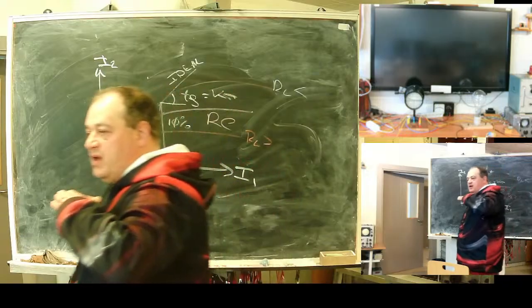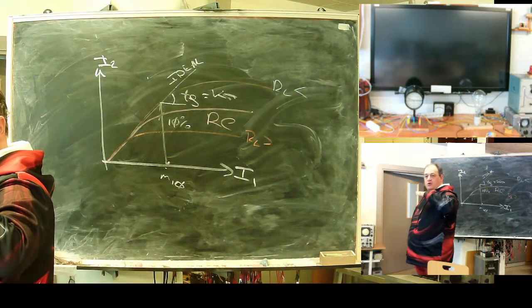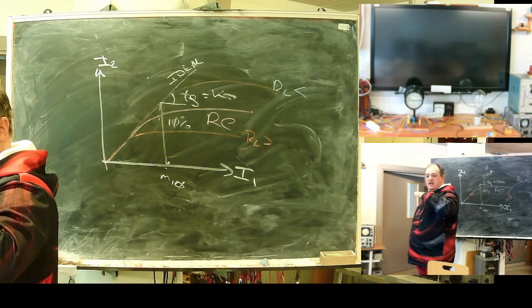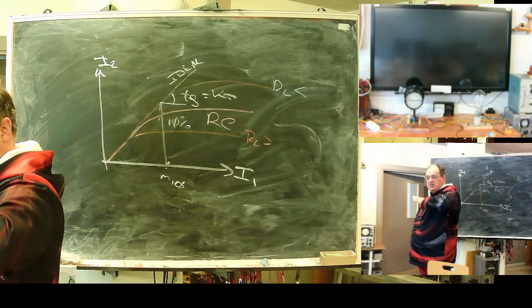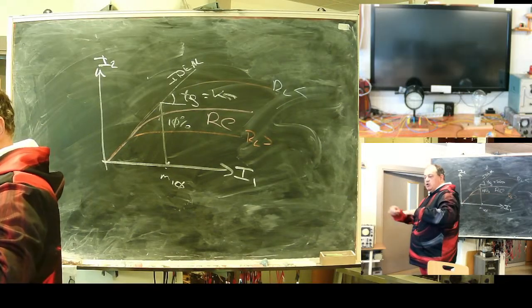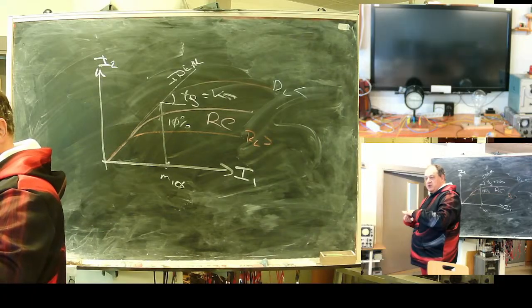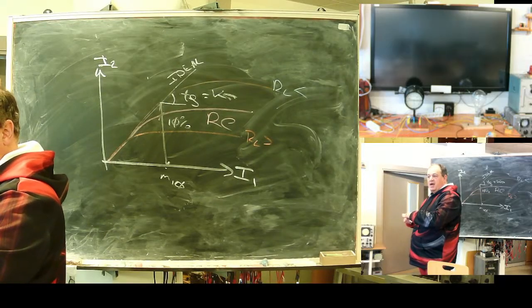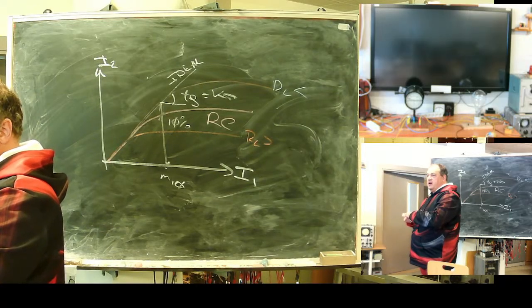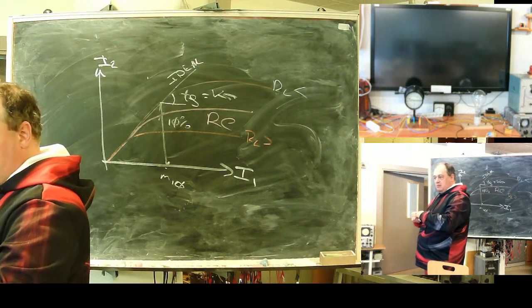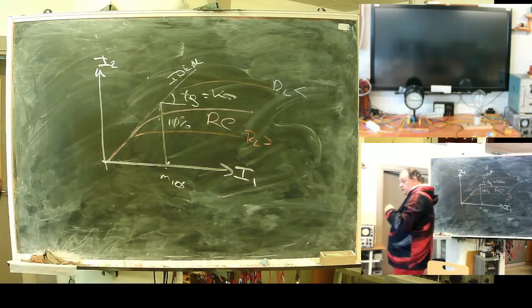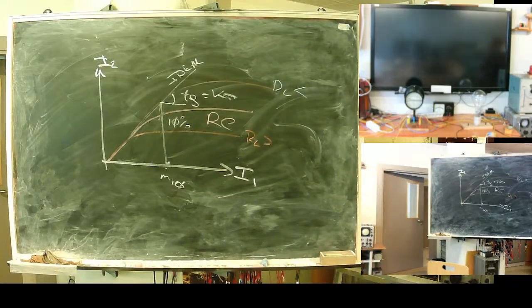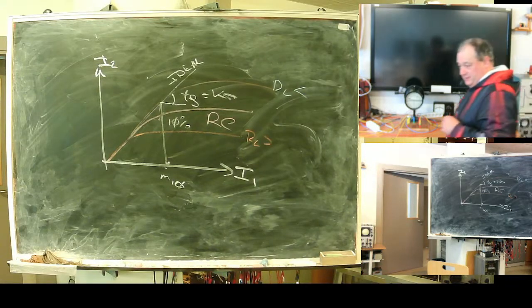At this lower current level, your operation range starts. It's a bottom line. This bottom line of signal processing should be above the expectable noise from your power supply. This determines the lowest possible load for your current transformer. It's not obvious, it's a fact.